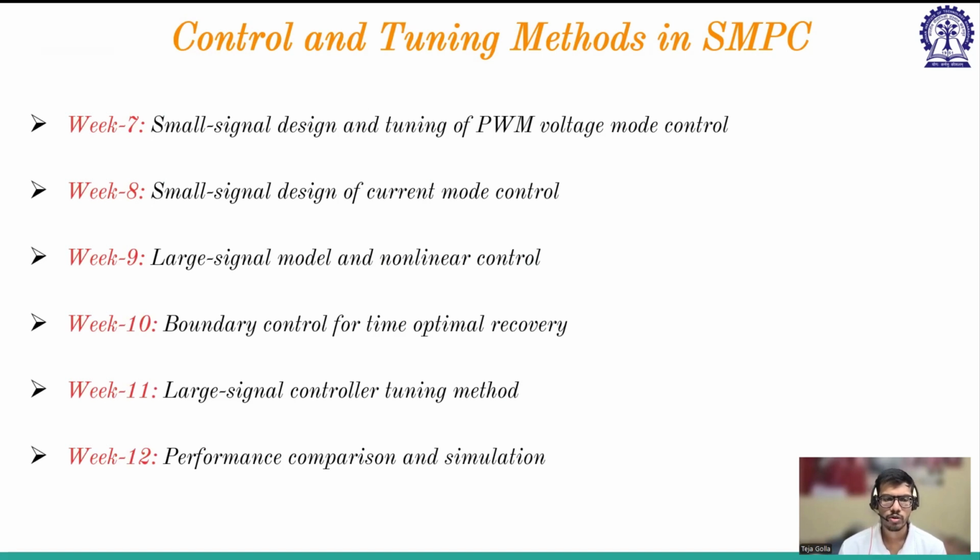So in this course, you will be extensively learning about starting with modeling of a converter, then how to design it, power stage design, then how to implement it in MATLAB using Simulink blocks, then running it in open loop, then how to get the model for closed loop, whether it be voltage mode control or current mode control, how to design the controller, and then implement it in the MATLAB, and then checking its performance. So this is under small signal design.